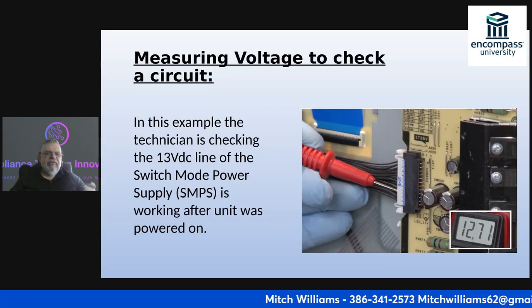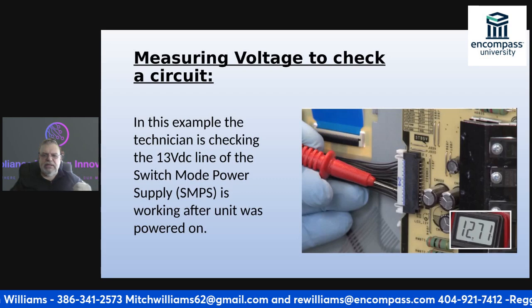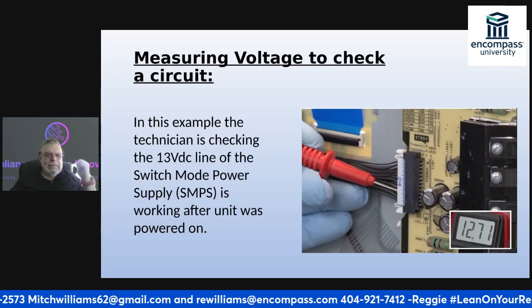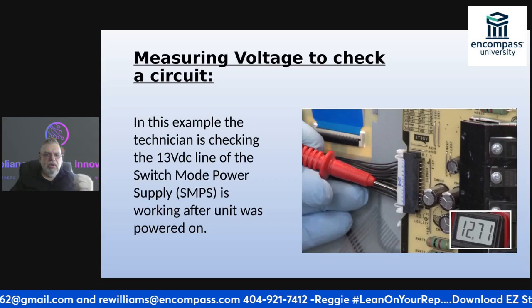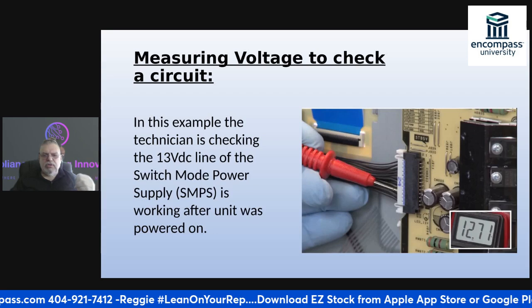Okay. If I'm checking voltage to check a circuit, this is an example. A technician is checking 13 volts DC on the power supply to see if it is working after the unit was powered on.